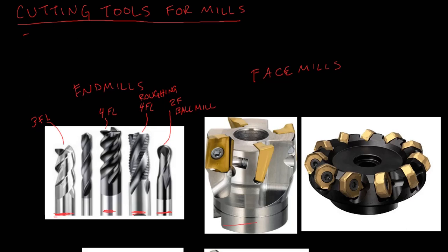These look like high-speed steel here without any coating on them, and then you have this black coating, which is not a paint; it's actually some sort of ceramic coating that increases wear resistance. So it reduces wear of the tool, which makes the tool more accurate and a batch of parts more precise overall.